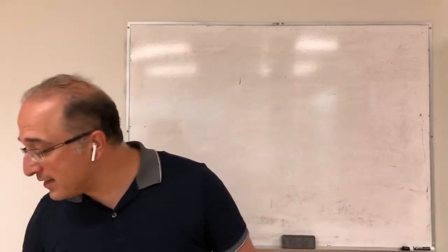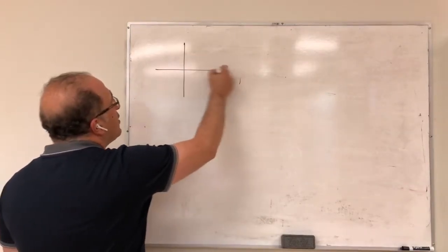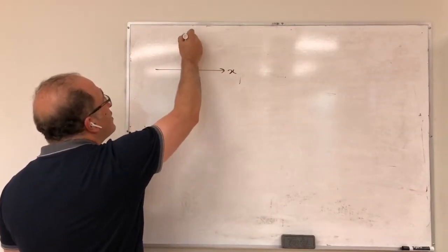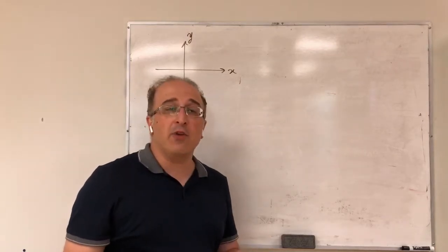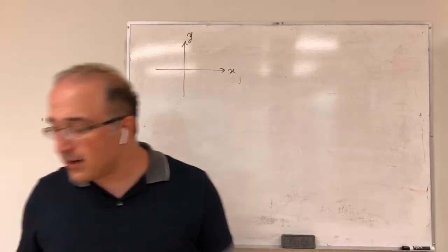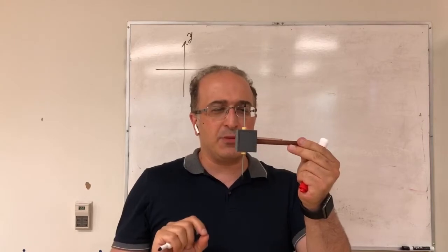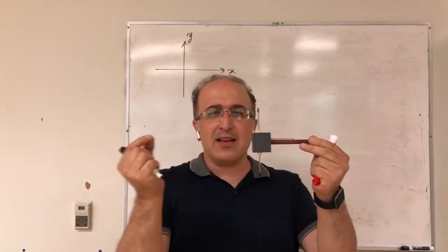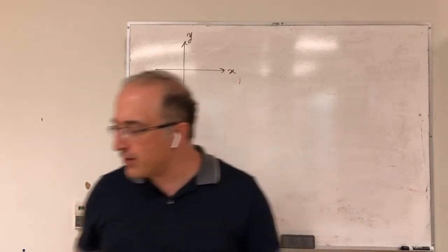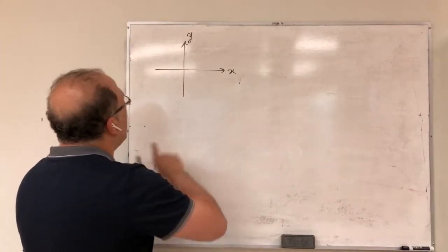So in that case, if I plot the xy plane, I want to know how the antenna radiates in this xy plane. And if you look at this antenna structure and forget about this piece for the transmission line, if you just look at the antenna itself, if you are here or here or here or here, you see the antenna the same thing. So you expect your radiation pattern to be something like that.